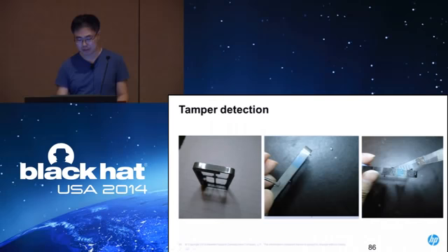And the cable is using some kind of paint that can pass the current through. So if you try to tamper with it in any way, it will cut the cable and break the connection. In that way, the chips inside the Verifone device will know that the cover has ever been opened.